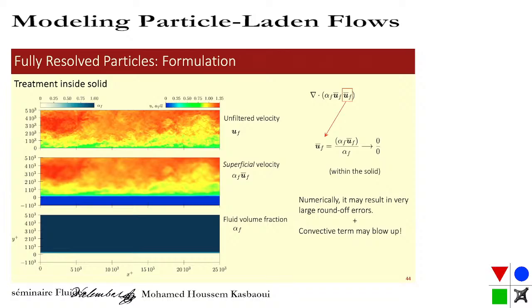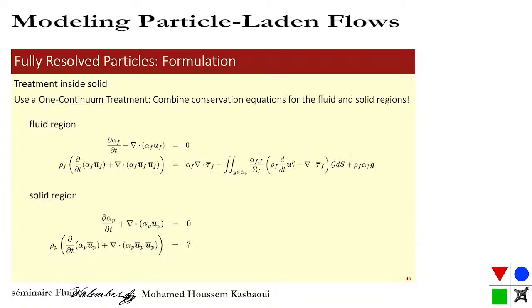Well, you try to avoid the volume fraction formulation. So how do you do that? Well, you do a one field method, or you do a one continuum. I'm just going to call it one continuum. I think in liquid gas methods they call it one fluid formulation. So I'm going to just call it one continuum treatment here.